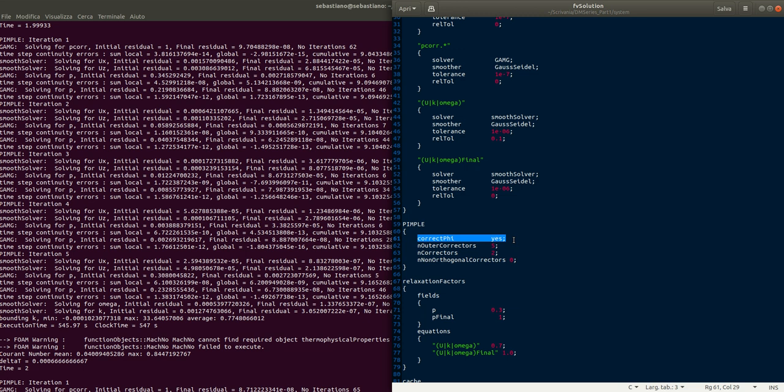But if you deform the cells, still with 0 velocity, you have a net flux into the cells, which is not correct, because the mean cell value must remain constant. So basically this correction adjusts the flux in order to be 0 even if the mesh is deforming.